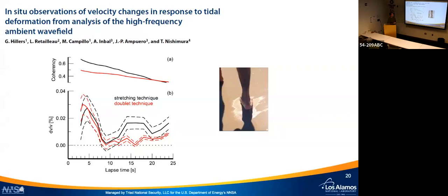So this is like a dilatant material, and it's the same thing as when you step on the wet part of the sand at the beach and the water around you seems to dry out. I don't know if anybody's ever noticed that, but it's not because you're squeezing the water out. It's actually the opposite. By compressing the sand, you're opening up the pores, and then the water gets sucked in there, and that's why it looks dry. So you're not squeezing the water out, you're drawing the water in under your foot. But that's what they observed in California.